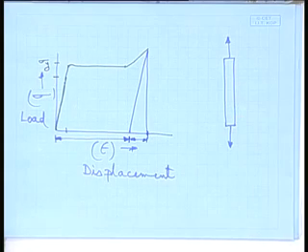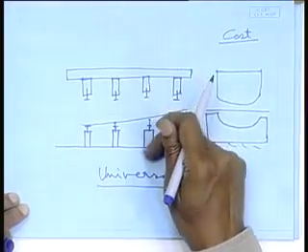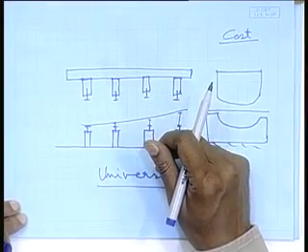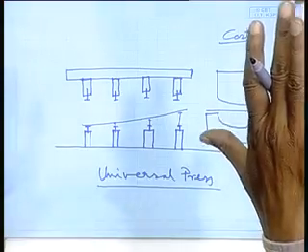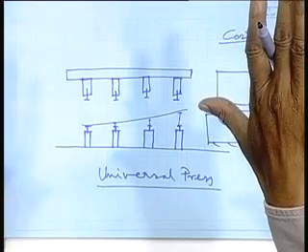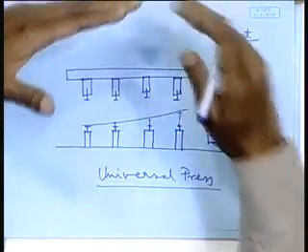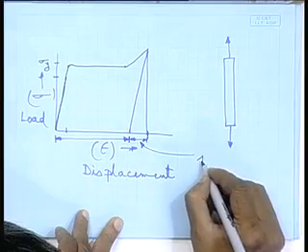That means when it is under pressure from both the top and bottom area of hydraulic jacks, it will perfectly conform to the required plate shape. But the moment I release the load, it will straighten out, so called it will spring back, right. So, this is my extent of spring back.